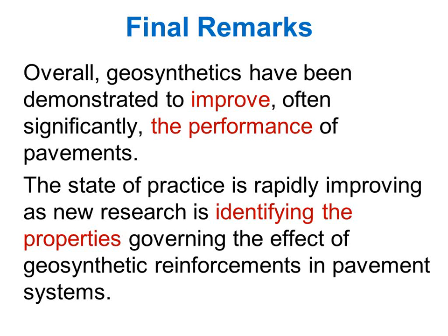So I could say that this is real data, but it is a stretch to say lime treatment does not work. I could say that there is evidence that you should be careful. So far in Texas, if you have expansive clays, you could treat the subbase, period. Now they are rethinking that.